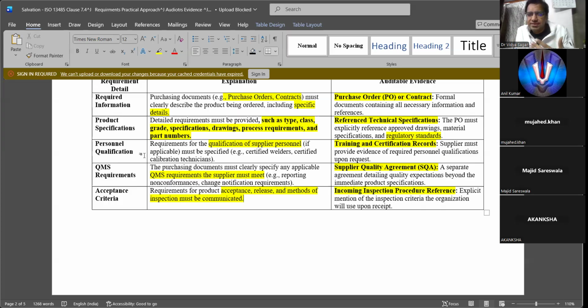And the most important thing is, as I said, you have a quarantine. Okay, suppose you get a non-conformity material not meeting your specification. You have to be careful that that material won't mix up with the other material. So it has to be totally segregated outside in the quarantine, or segregated outside as a non-conformity product. Are you getting my point?